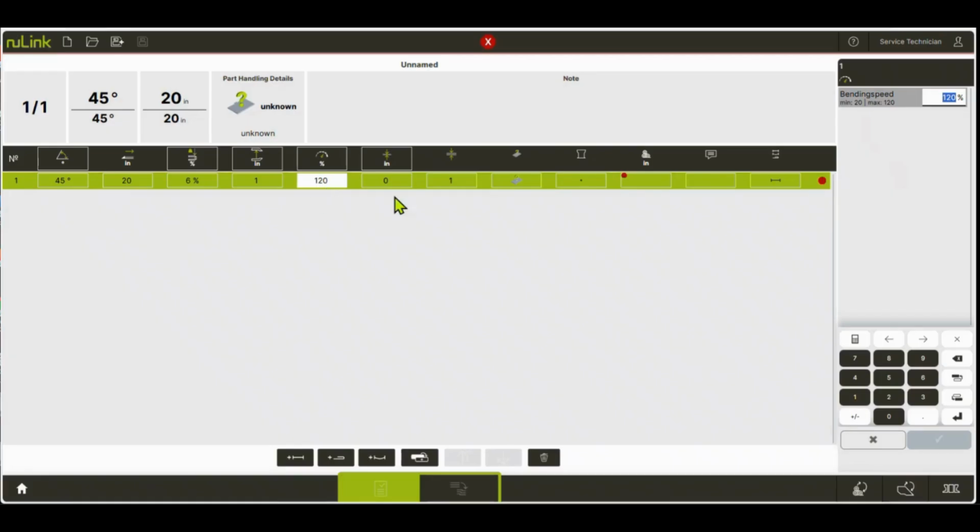All right, this next column here is if you have a machine with automatic material thickness adjustment. This is where you control your bend center and where you can control your bending beam depth. The model that this one is attached to does not have that feature, so this value for me in this class will be set to 0.